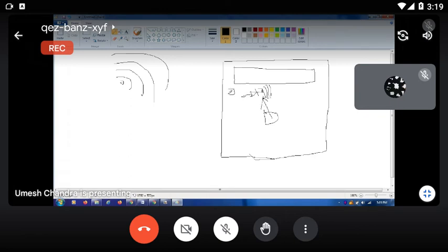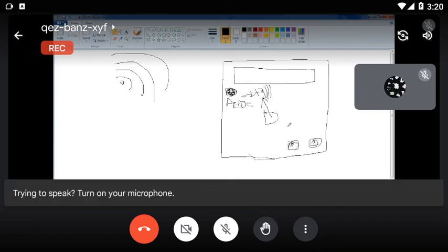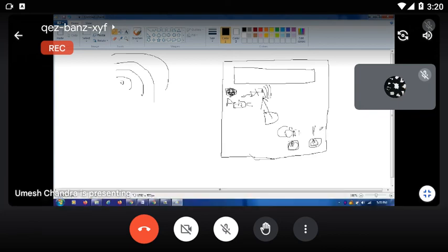And here is one blue button, AC/DC. When you test the continuity of the lead or probe, you just press the AC/DC button. Then after that, how do you check? Here are two points. One point is common, COM, and another point is V or ohm or capacitance measurement. The common position is your black lead.